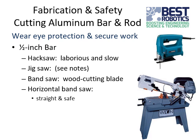Again, with these, make sure you're wearing eye protection, and make sure you're securing your work. You don't want little bits of hot metal flying out and hitting you in the eye. You should be able to cut that. Aluminum in general is a really soft metal, so it's relatively forgiving and relatively easy to cut for being metal.